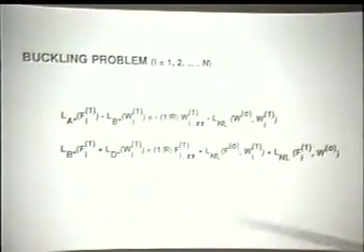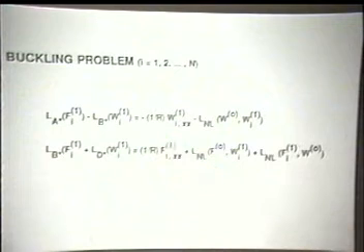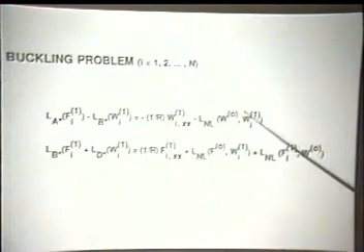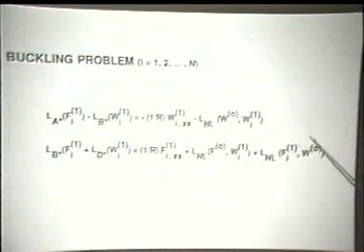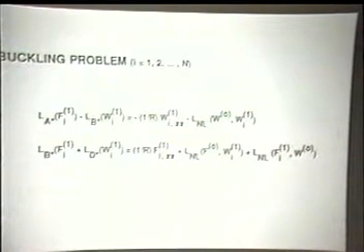The buckling problem, as indicated here, is a problem for the first order field. It is a linearized equation for the first order fields. And notice here, here, and here, we have contributions of the pre-buckling problem. Now, if the pre-buckling problem is rigorous, then W super 0 and F super 0 are functions of X, and then here we have variable coefficient equations.